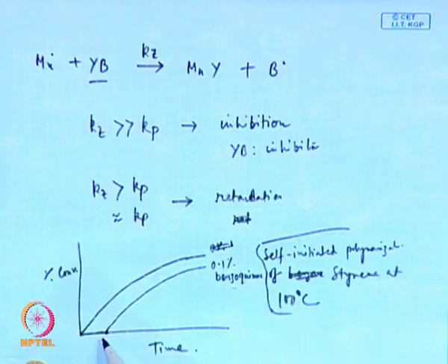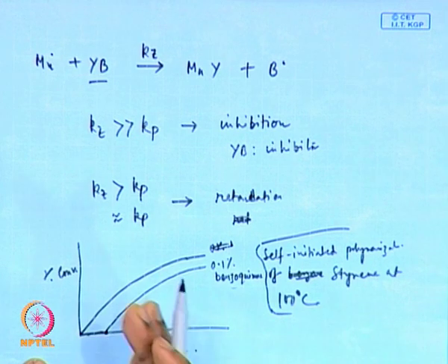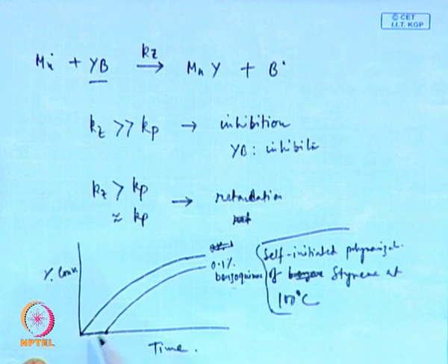So, when you do a reaction, the best way is to distill out that benzoquinone or hydroquinone stabilizer, or you can add a little excess initiator compensating the inhibitor molecule, so that the reaction does not proceed till all the benzoquinone or hydroquinone is consumed. After that, normal reaction happens.